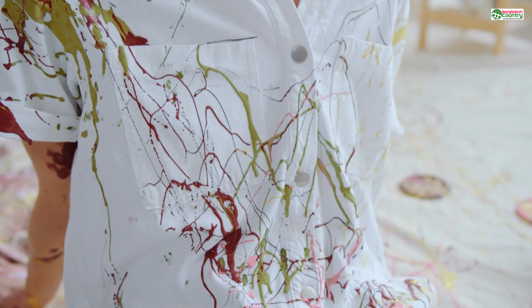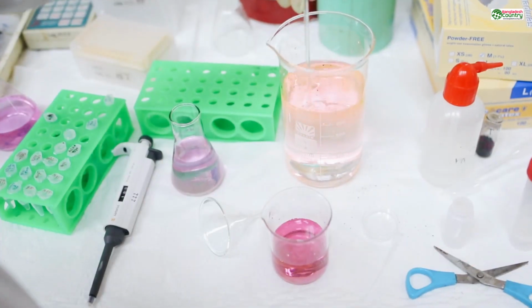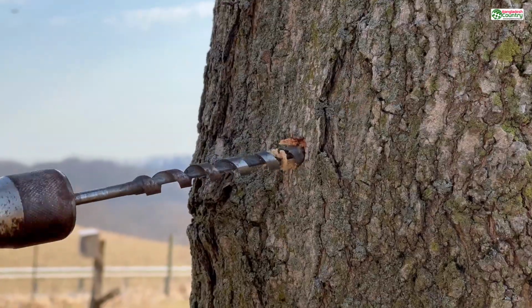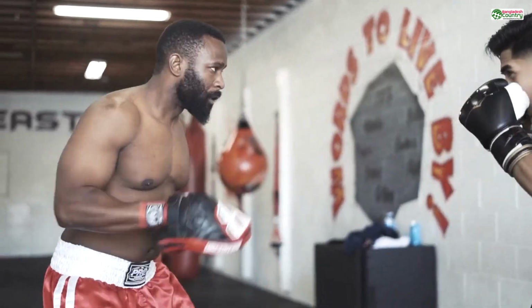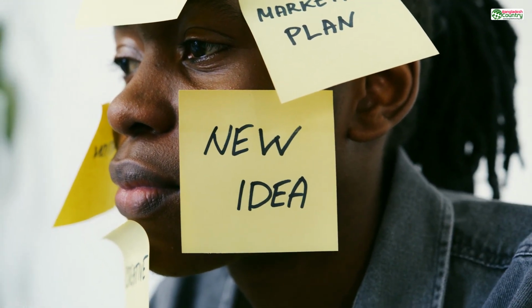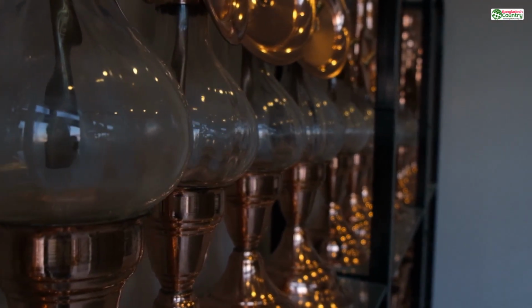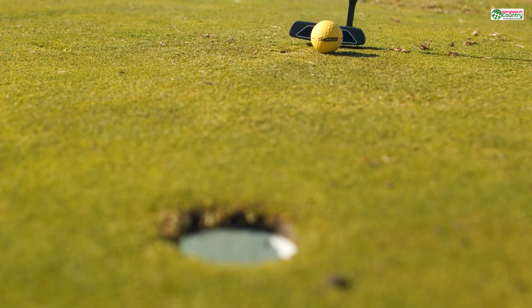But the solution is incredibly simple. Escape holes, sometimes called drain holes. You must punch at least 2 holes in your hollow model. Why 2? Think about trying to pour soda out of a can with only 1 hole poked in it. It glugs and sputters because air can't get in to replace the liquid coming out. You need 1 hole for the material, be it trapped powder or liquid resin, to escape, and a second hole for air to get in and allow a smooth, easy flow.